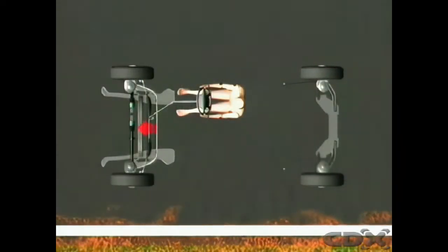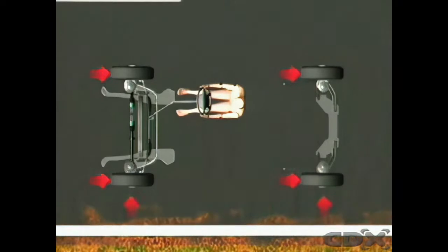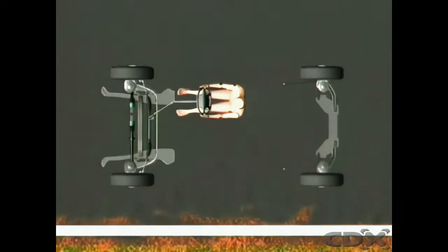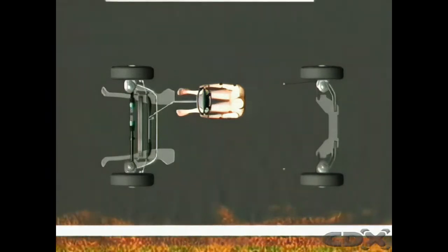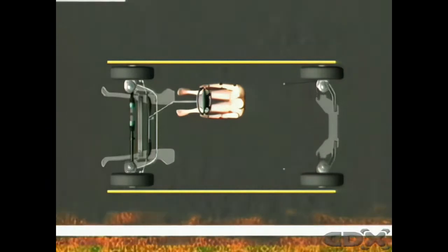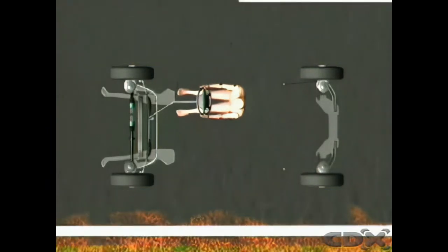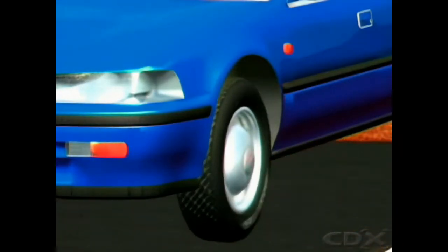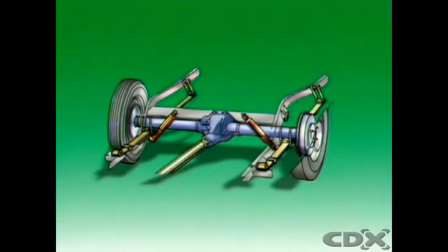When a vehicle is in motion, several forces operate to displace the wheel units: driving thrust, braking torque, and cornering force. These forces must be transferred to the frame of the vehicle, but while they act, the wheel units must stay aligned with each other and with the frame. They must be located longitudinally and laterally while still having the freedom to move vertically to allow for suspension travel.